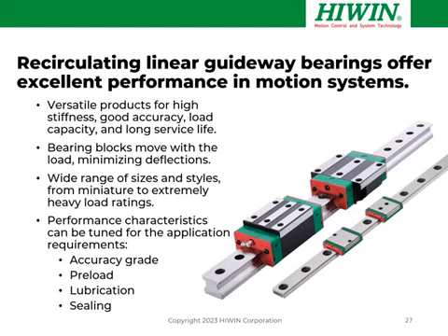In the linear guideway, the bearing blocks, which are compact, move with the load. So the reaction of the bearing load to the payload is constant. And you can have multiple bearing blocks on the same guideway, and you can have multiple sets of guideways to uniformly support your load. They're available in a wide range of sizes and styles, from miniature, only a few millimeters in size, all the way to very large, very heavy duty supporting tens of kilonewtons.